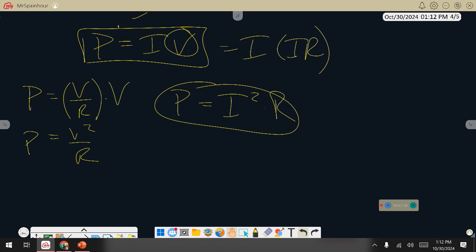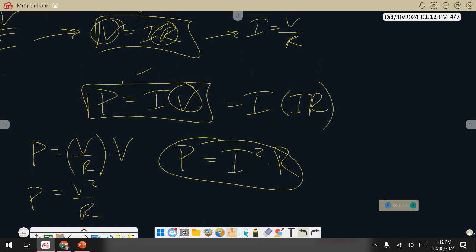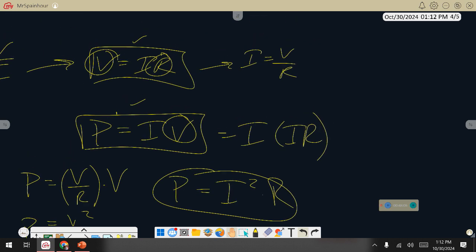Why would voltage matter more? Well, let's see. I said I double the resistance and I double voltage. Well, if you come up here, in that math equation, yes, but if you come back up here to understand why, if I doubled voltage and doubled resistance, what effect would that have on current? Oh wait, hold on. Current would stay the same, yes? But in this equation, current stayed the same, but what did the voltage do? Doubled. So what effect should that have on power? It should still double. You're definitely getting problems like this almost identically on the test.